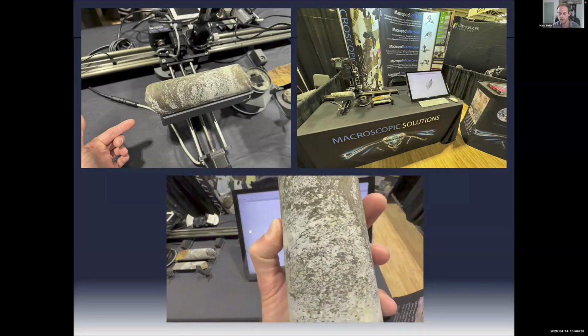But it's really, really good to show this because it also demonstrates some of the capabilities of Metashape, where you do not need to capture the entire specimen in the field of view in order to do this. I did not have to render the panoramics before I processed this. I took image crops of the core sample, stacked just those crops, and then I imported all of that data into Metashape, and I was able to get a very, very accurate rendering of the 3D model.